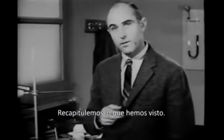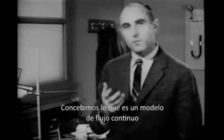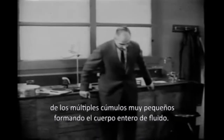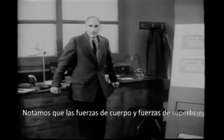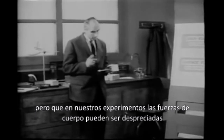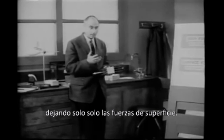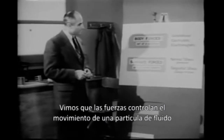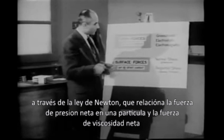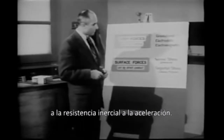Let us go back over the ground we have covered. We conceived the model of a continuous fluid, and then we focused attention on one of the many very small lumps forming the entire body of fluid. We noted that body forces and surface forces act on every such fluid particle, but that in our experiments, the body forces could be set aside, leaving only the surface forces. We resolved the surface forces into two components: pressure forces acting normal to the surface and viscous forces acting tangentially to the surface. We saw that these forces control the motion of a fluid particle through Newton's law, which relates the net pressure force on the particle and the net viscous force to the inertial resistance to acceleration.